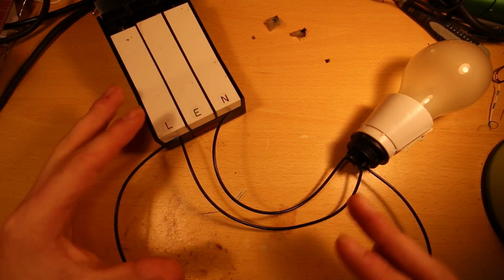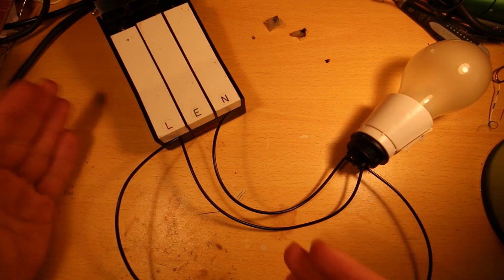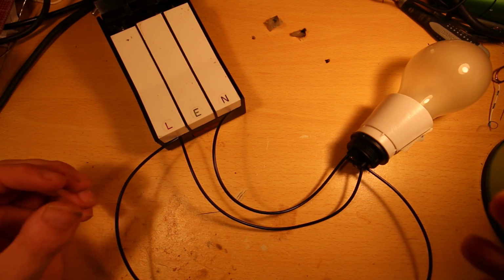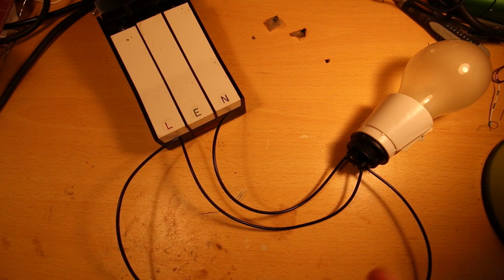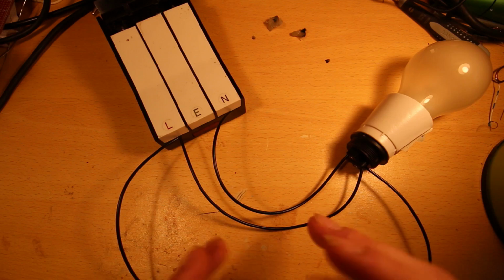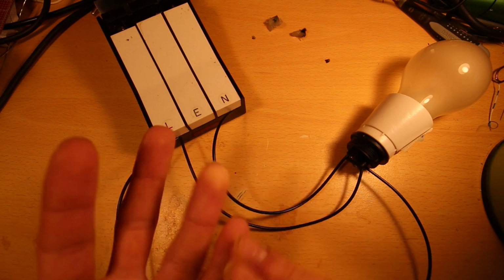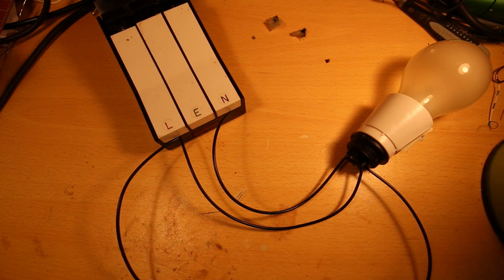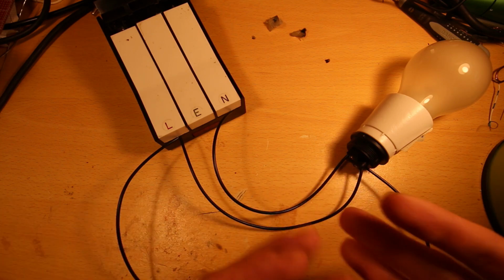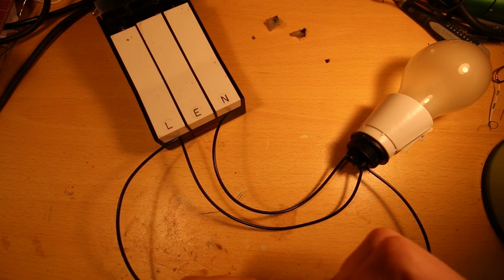I'm going to use this demonstration to show that current will flow by all possible paths in a circuit and not just the shortest path or the path of least resistance, which is a common thing that I see people saying, and I'm going to now prove that they are all wrong. The path of least resistance thing is a massive oversimplification. As I showed, things like air and plastic and every single piece of matter will conduct electricity to some degree, usually not very well, but it will conduct some. So some current will always pass through them. It's just usually such a small amount of current that it's not worth taking into account.